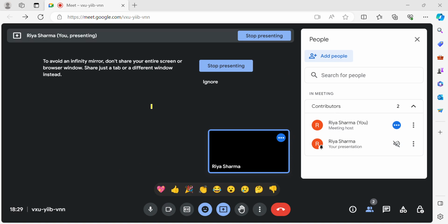Write what is given. Heat given, so Q is equal to plus 8, to an open system, while its internal energy decreases, so delta U is equal to minus 12.